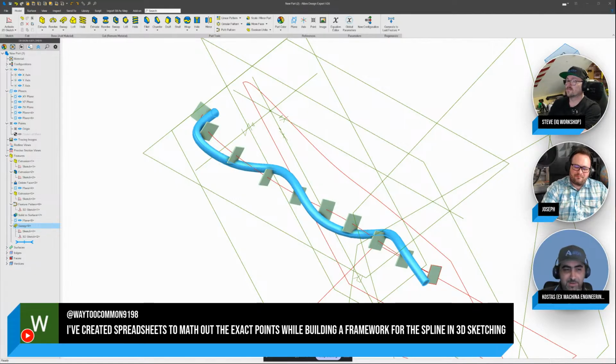If you see my Excel for Engineers video, at the end, I do an example of G code, and you can see that I plasma cut a few holes for a flange, and if you see the entrance and the exit for the plasma holes, it seems to rotate around with the position of the hole, and that was done through a transformation matrix. That was handled by Excel. So once you get that deep in it, you can do some amazing stuff.